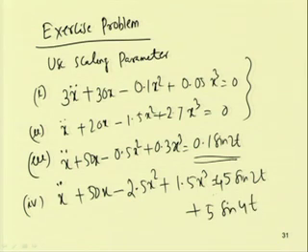In this case, for the forcing term 45 sin 2t, the coefficient is of the same order as that of the linear part. But the coefficient of this other forcing term is 10 times less than that of the linear part. That is why one can use a bookkeeping parameter epsilon in this case.